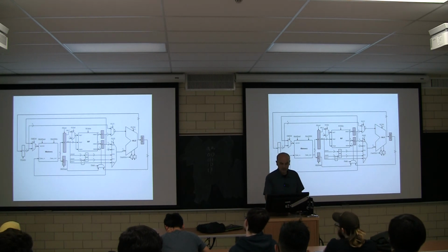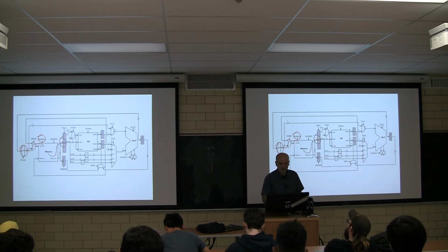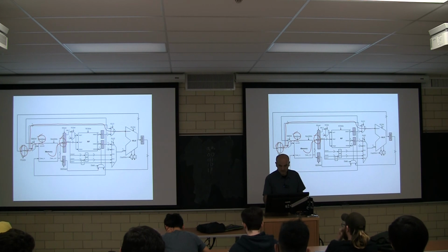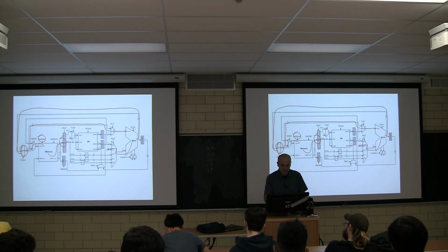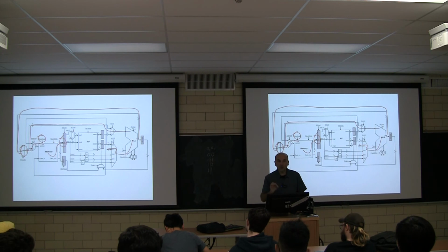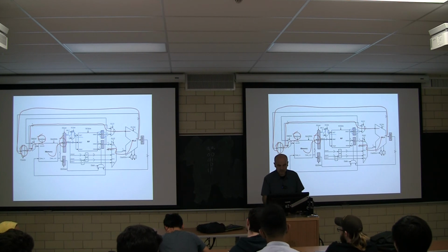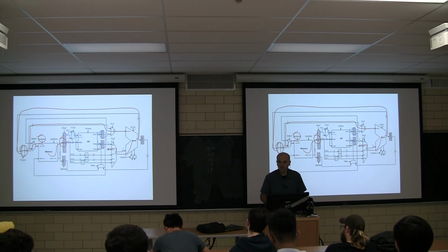So first clock cycle, you take the PC, you go to the memory, you do a memory read, and you load into IR. You also do PC plus 1, first clock cycle. Fair enough? Second clock cycle, you look at the instruction. You cannot take action yet. So you naively go and you read 2 registers, just hoping that this is going to be useful.